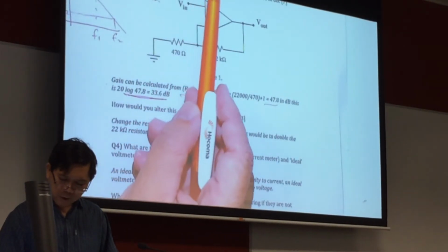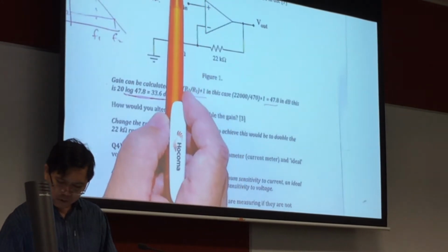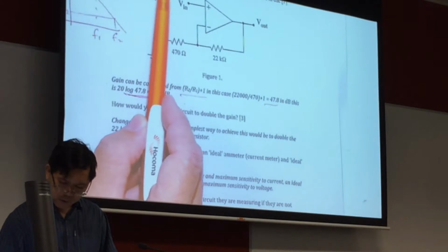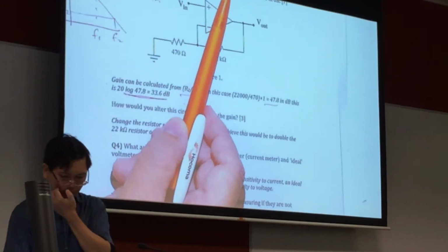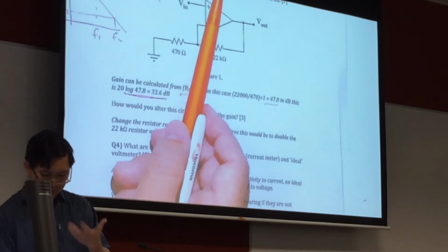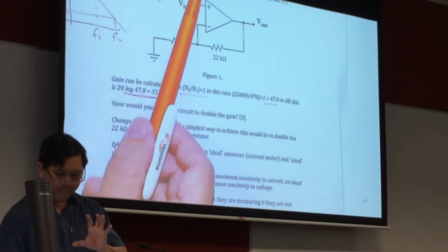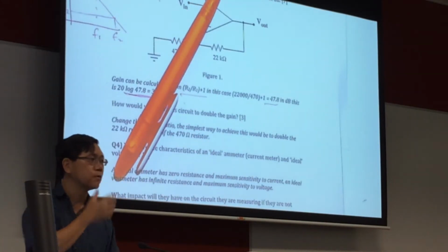Connecting the output to the non-inverting input is called positive feedback, acting in the opposite way of negative feedback. Positive feedback creates a conditional hysteresis, or we call it latches. It doesn't mention what, but basically, as I say, this will allow you to have very nice noise immunity. Okay?